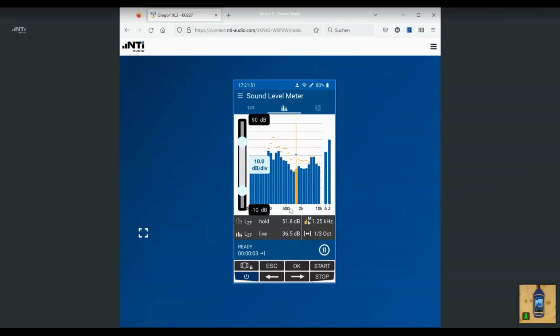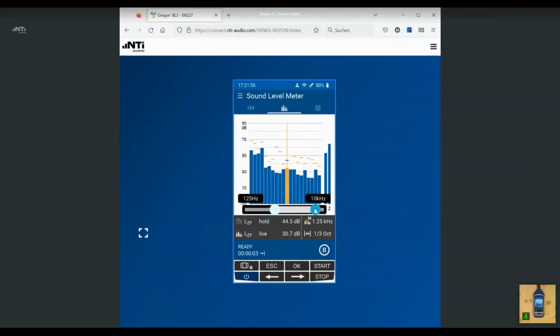So this allows me to exactly highlight that part of the graph I am interested in. And I can do the same here with the x-axis, which means I can restrict my spectrum to a number of bands, only the ones I am most interested in. And I can also scroll through that, of course. So let me go back to the original state.